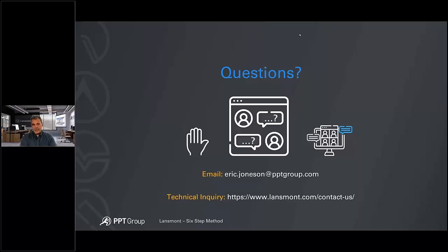It also depends on how, when you do fragility assessment, you're usually doing that in controlled orientations. So it's important to look at all the above. If your fragile orientation on your product is base down or top down or left side down, then you're certainly going to focus on potential events that happen in or towards that orientation. But you're right, you would look at the vector sum, and we report on the vector sum because all the instruments record triaxial data. So you get the triaxial resultant as a part of that vector sum.